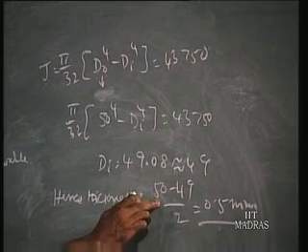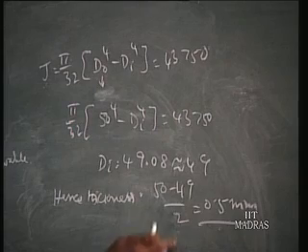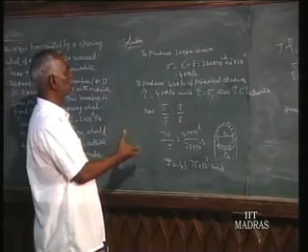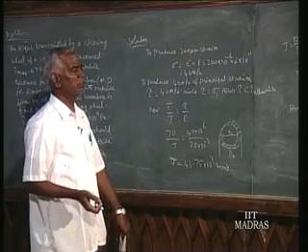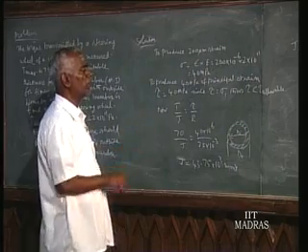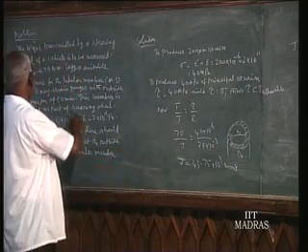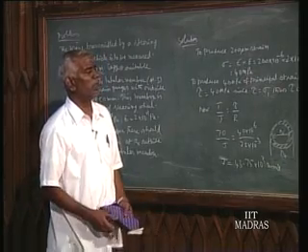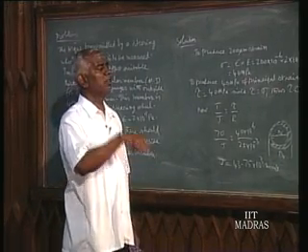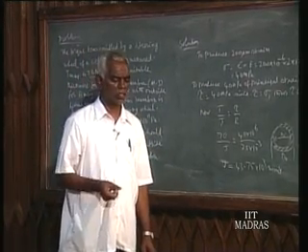So the thickness, with outside 50 and inside 49, is divided by 2, 0.5 mm. So that should be the thickness of the tube. Then only you will have sufficient stress and sufficient strain. Our instrumentation will have sufficient sensitivity so that we can measure the full range of the torque up to 70 Newton meter. So that is how we have to design the primary transducer, transducing the torque to strain.